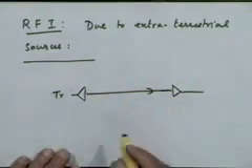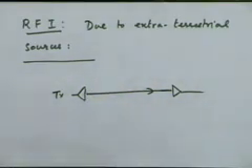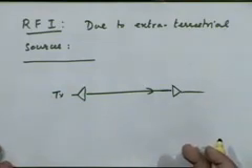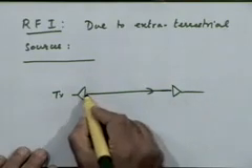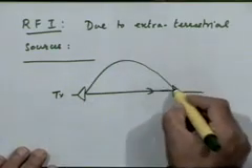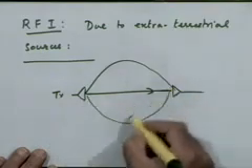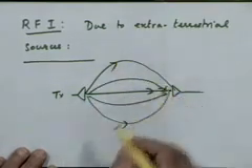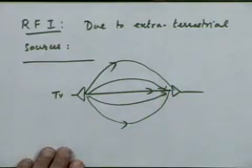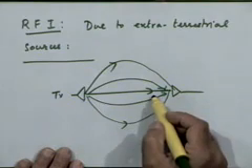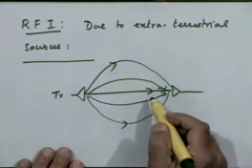But if, for various reasons, there are multiple paths between the transmitter and the receiver, the radio energy not only goes from one to the other directly, but maybe through some other indirect paths. Now the receiver is confused. It doesn't know which one is the right signal to look at.